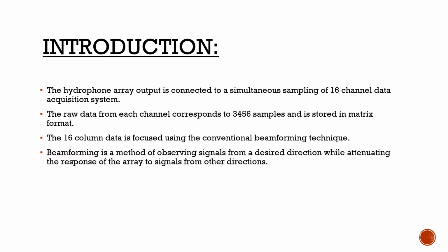The hydrophone array output is connected to simultaneous sampling of 16-channel data acquisition system. Raw data from each channel corresponds to 3456 samples. This is stored in a matrix format, and these reflections are provided by NIOT. The 16-column data is focused using a conventional beamforming technique.